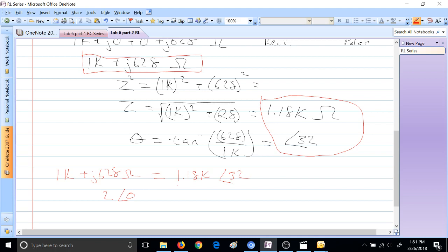Convert that to rectangular format if you need to add, or keep it this way if you're going to multiply or divide. And we're using the same formula of E is equal to I times impedance. All right, so nothing has changed. The only thing is now we're working with rectangular or polar notation, and these concepts should be nowhere near difficult for any of you to actually understand.